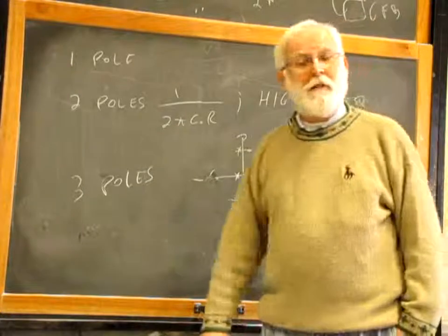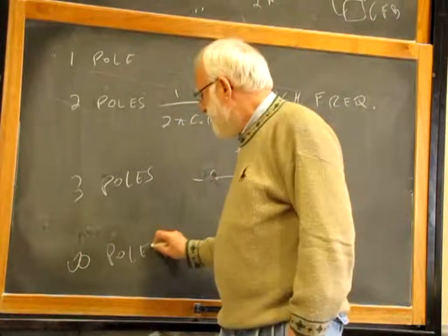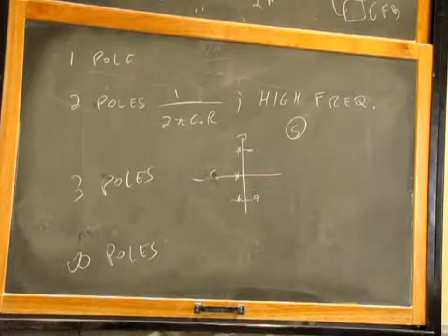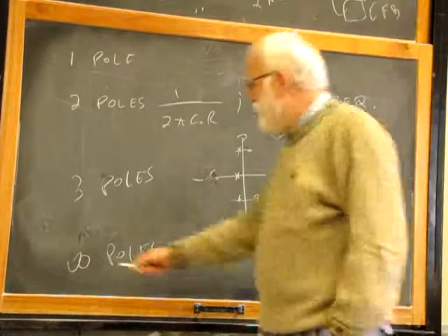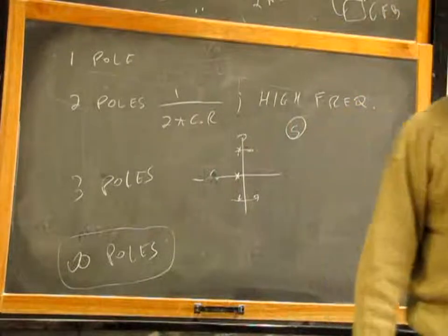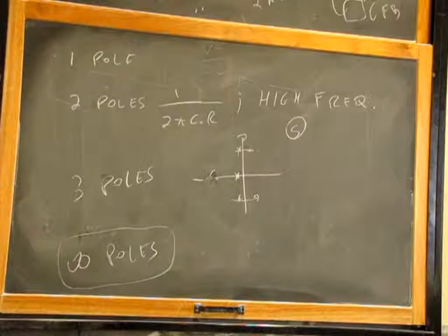And then somebody else came out and said, no, everything is wrong. You have an infinite number of poles that are quite hard to compensate for because you never end up compensating for them. Actually, this infinite number of poles is just a time discrete representation of our system. Instead of using Laplace transform, we use Z transform. In Z transform, you can describe your system very well, but when you go back from Z transform to the Laplace transform, you have an infinity of poles around the vertical axis or something like this.